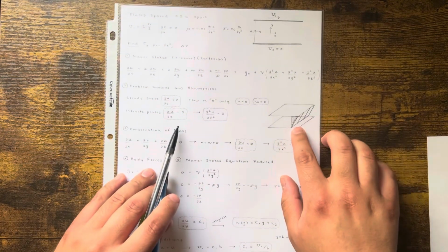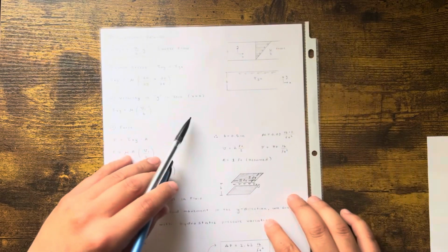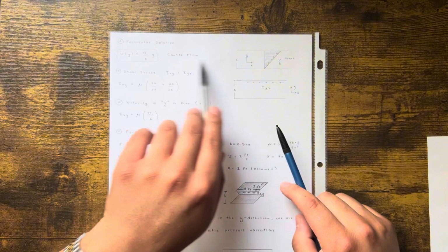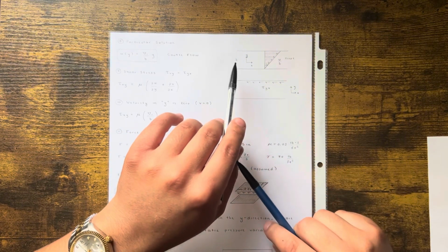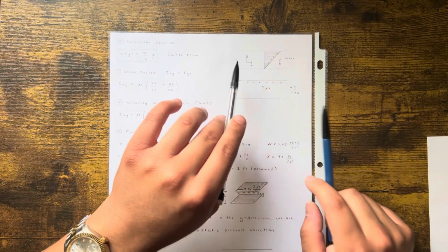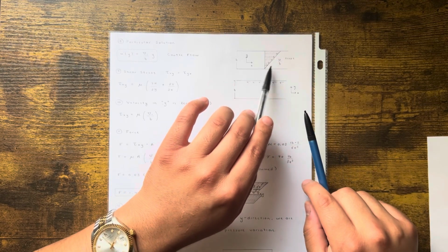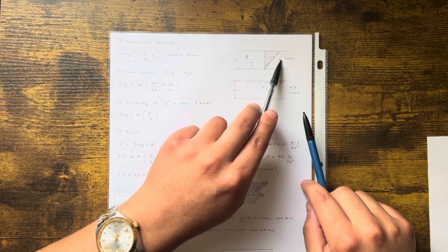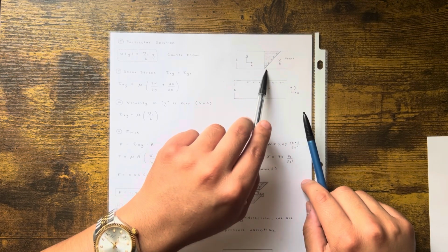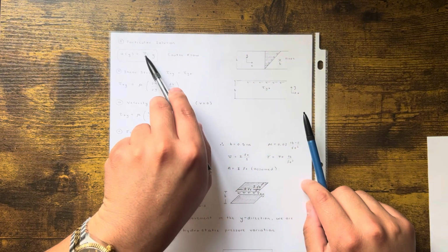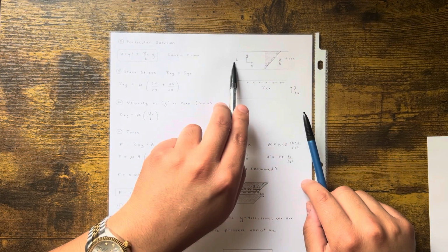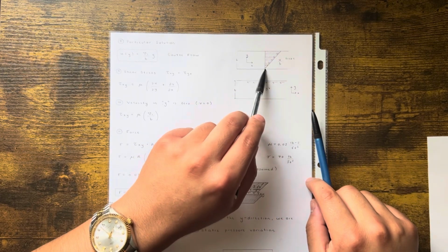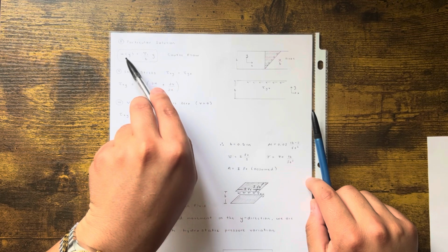Remember this assumption? Believe it or not, when I first did this problem, I did assume it. I didn't do it and then say, oh, I'm just going to put that diagram on there to make it seem like I'm smart. No, it really is just that simple. Our slope in this case is U1 over B. So U over B, I should have put U1, but it's okay. It's linear. So we know U1 and we know B, right? 0.5 inches, and this U1 is 2. So we know our slope, and then for every y, you should be able to get the velocity profile.